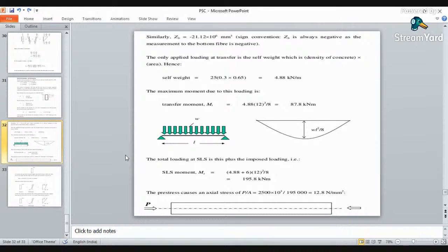Okay, so here first stress will be direct stress, that is P by A. Second stress will be stress because of the external loading. Okay, we do not have to consider the stress because of the eccentricity of the tendon, that is because of the bending. So final stress will be stress because of that axial loading, that is P by A, or the direct stress.